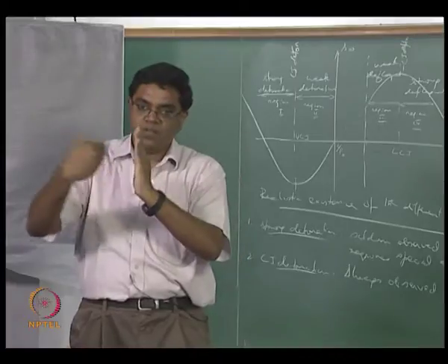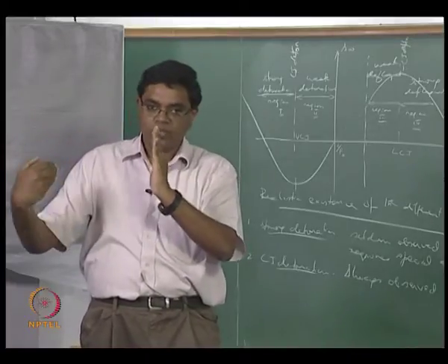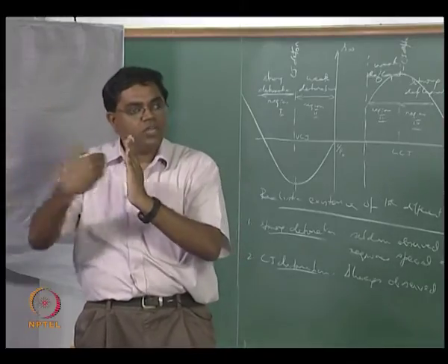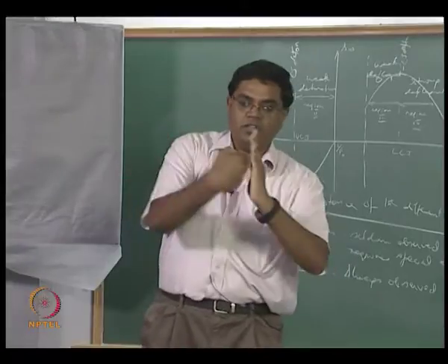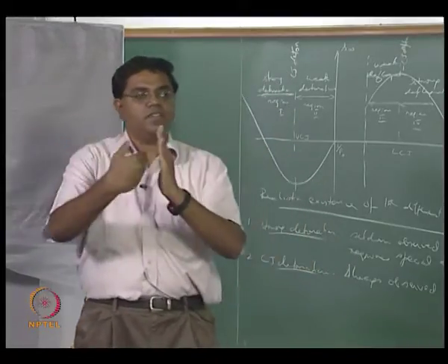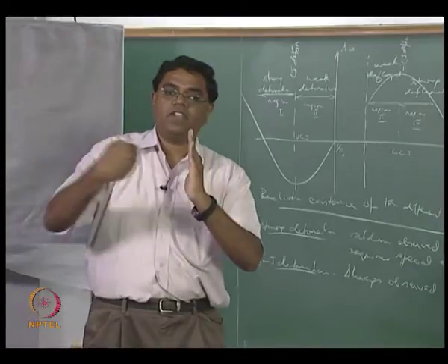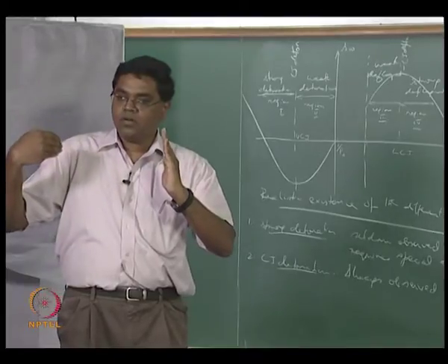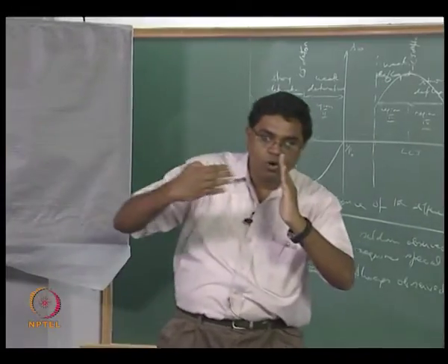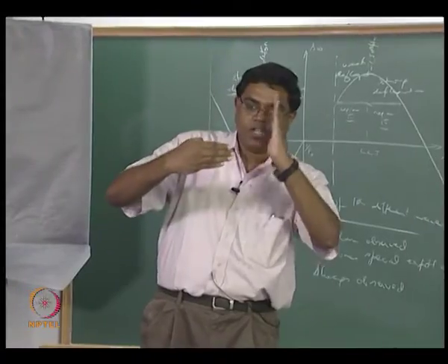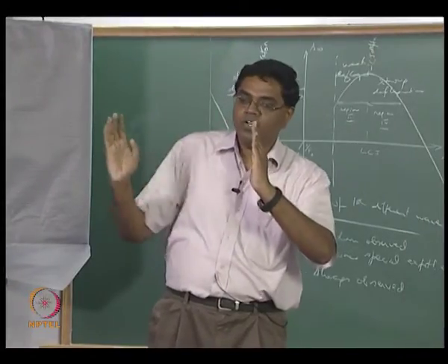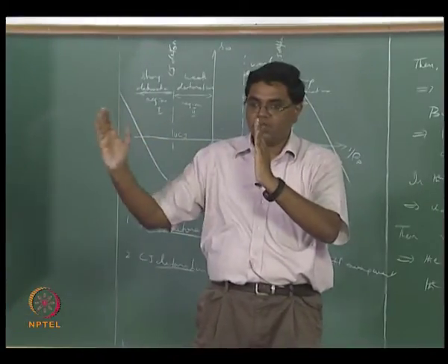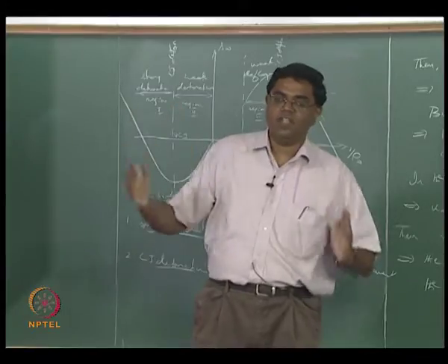You now have a subsonic flow downstream, right, and you now have the pressure pulses that go and get reflected from this and begin to come back and hit the wave, because this is a subsonic flow and the pressure pulses can actually propagate faster than the product flow. Product is actually beginning to follow but at subsonic speeds, and it's not going to catch up, but it can allow for the waves to go, the pressure disturbances that are coming from the other side can actually pass through this because this is subsonic.